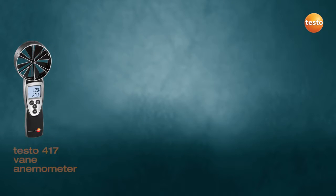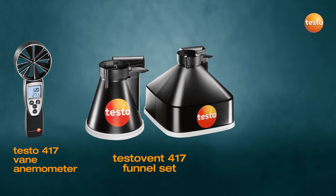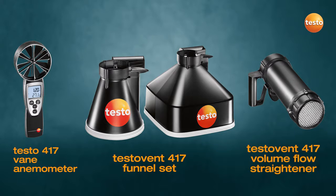You will be perfectly equipped for taking measurements at supply air and exhaust air outlets of a room ventilation system with the Testo 417 vane anemometer. It can be combined with two funnels, allowing volume flow measurement at grills and diffusers, and thanks to the Testo Vent 417 volume flow straightener, it is also suitable for swirl outlets.